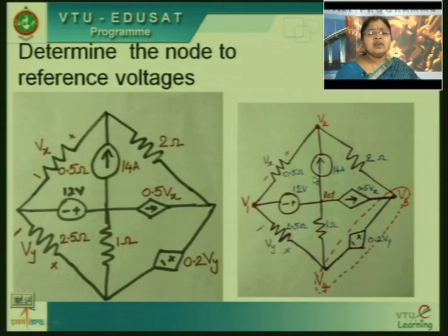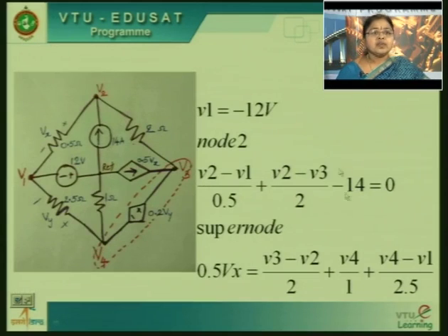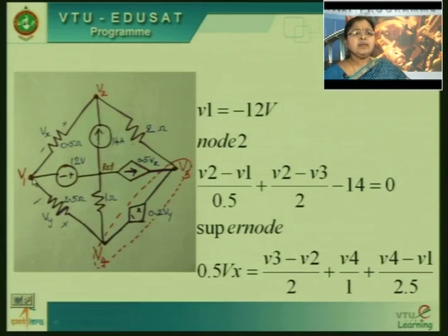Now, let us see how to write the equations, what all there is in this circuit. This is the circuit, and we have given the node names here because we have 4 independent nodes. So, 4 equations we have to write. Let us come to node 1. This is node 1. If you see node 1, actually 3 branches are connected to node 1, but out of these 3, there is one voltage source between the reference and node 1.